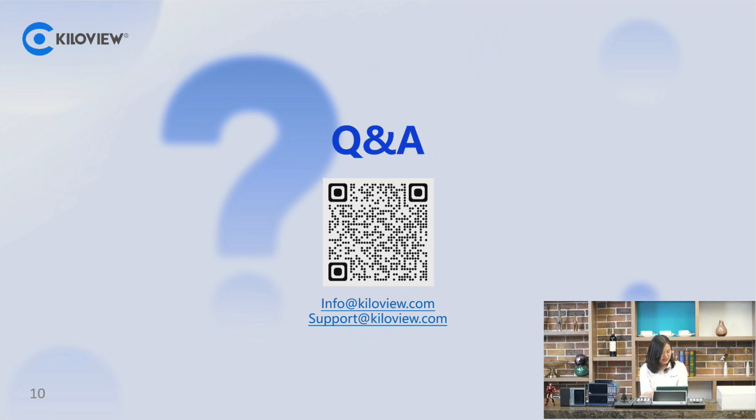So Sia, I saw, is there any encoder that will do SRT interlace encoding? I have to say, currently our E1, E2, and even the E3 can support this: if the video input is interlaced, we need to de-interlace it into progressive first, and then we do the encoding. That's because the chipset we are using right now for the E-series cannot support interlace encoding. But in our roadmap, we also have a plan to release a series of high-end encoders that can, of course, support interlace encoding for SRT.